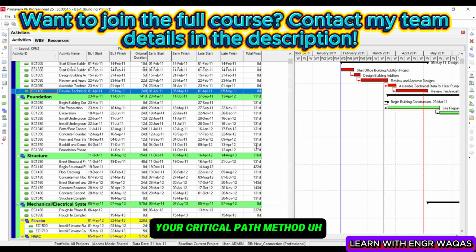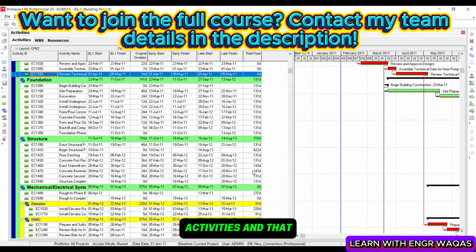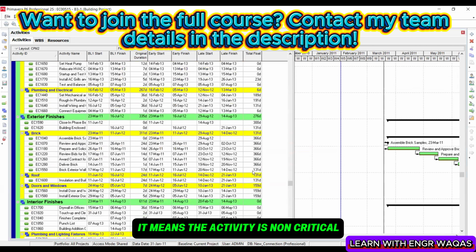Your critical path method is totally depending on two factors. The dependency of your activities, the link-ups, and the second thing is the assigned duration. As soon as you change any relationship, your critical path method is going to change. Zero in the total float column means critical activities, and total float greater than zero means the activity is non-critical. Okay, that is all.